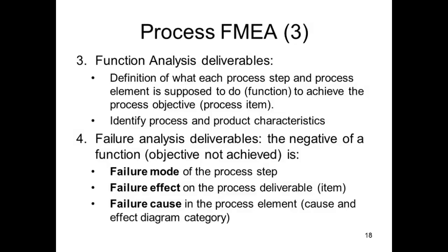That is, what was the process step supposed to do that it didn't do? The failure effect is the consequence. What is the consequence for quality? Like, well, the final assembly doesn't work. Failure cause is the process element that causes the failure mode, previously known as the failure mechanism.